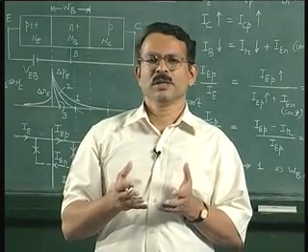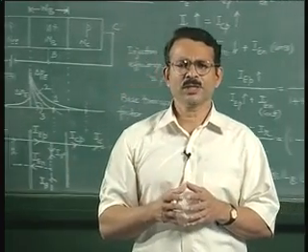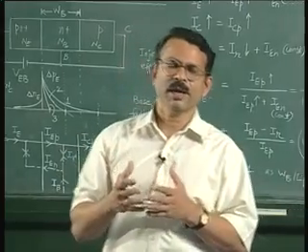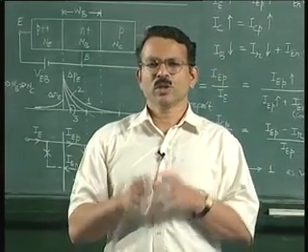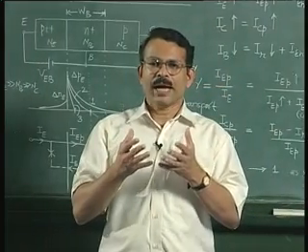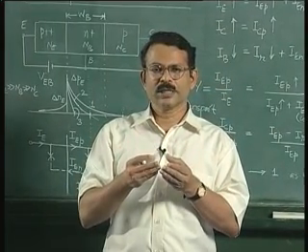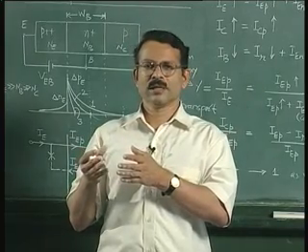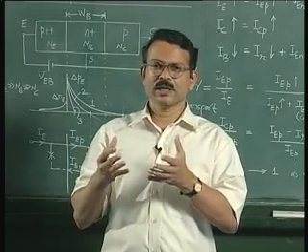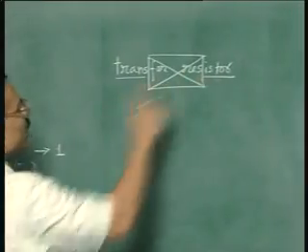So for example, the power is I square R, depends on the current and the resistance. So higher the resistance, if the current is same, higher the power. So because of this particular action of transferring of the current from a low resistance to a high resistance, which looks like some kind of an amplification, to emphasize this fact, this device is called a transfer resistor or a transistor.